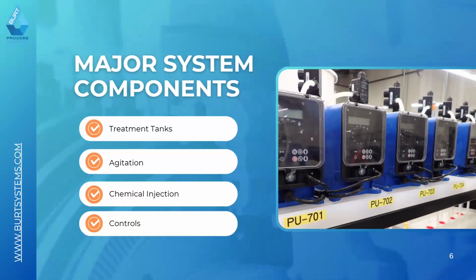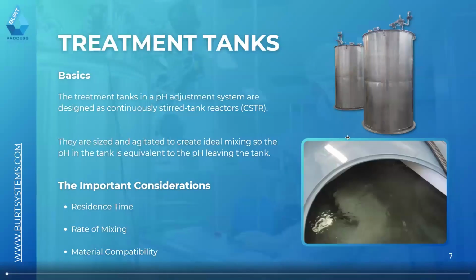Mixing calculations obviously get really into the weeds as far as complications, but a good rule of thumb is you're generally looking at about 1.5 to 2 tank turnovers per minute as part of any mixing in the system. So when you have things like recirculation pumps, those really aren't used as part of the actual mixing package. They're really meant to speed up the chemical injection that goes into your system.